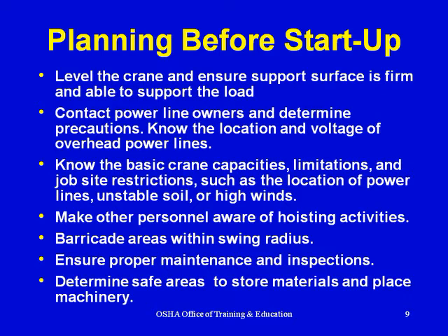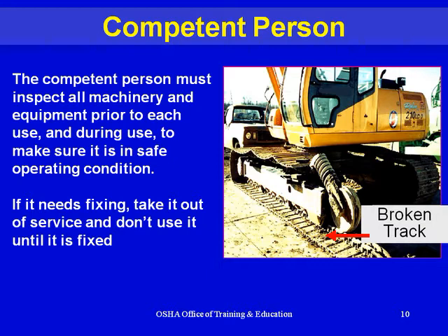Barricade areas within swing radius. Ensure proper maintenance and inspections. Determine safe areas to store materials and place machinery. Competent person. The competent person must inspect all machinery and equipment prior to each use and during use to make sure it is in safe operating condition. If it needs fixing, take it out of service and don't use it until it is fixed.